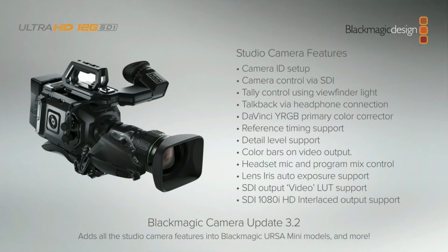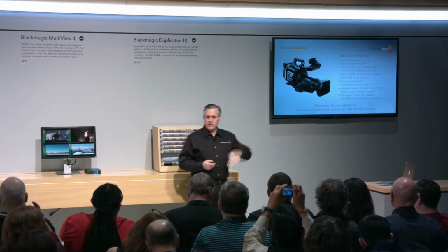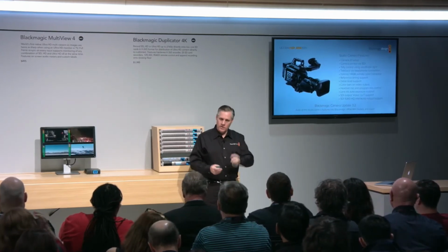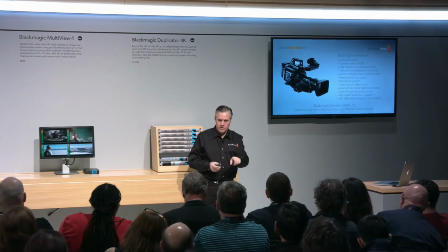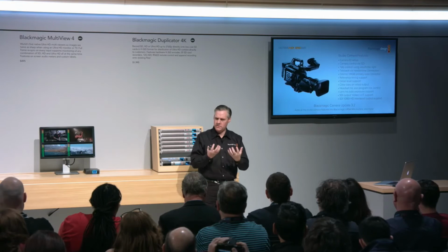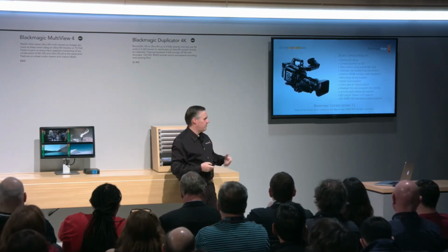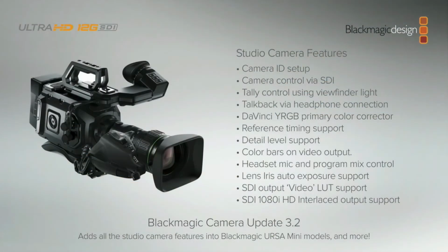Most people don't realize what a YRGB color corrector is, but you can adjust color balance without chasing gains. But the thing I like about it is you can pull the white up a bit. Most people don't realize it's in there. If you touch the Y indicator on the ATEM control software, you can adjust it and you can pop the white out. And it just sort of brings whites and things. It just adds a really nice depth to images. It's beautiful. The DaVinci guys know how this works and they love using it all the time.